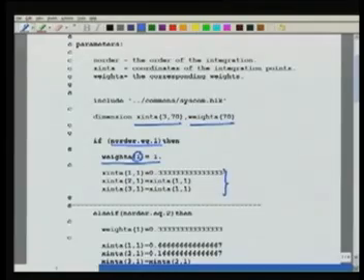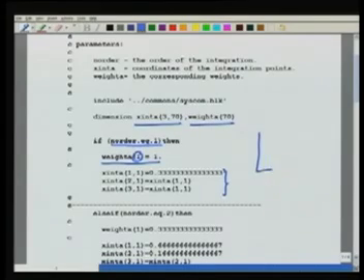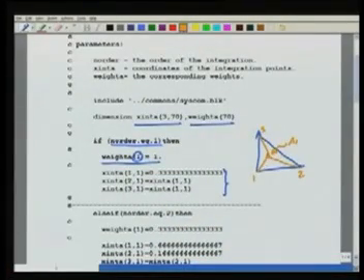given, has 3 coordinates, but we had only psi, eta. These 3 are actually given in terms of what is called the area coordinates or the barycentric coordinates, okay, which is very simple. Let's take any point, and this is my node 1, node 2, node 3. Connect these points. This becomes my area A1. So given any point in the middle or anywhere inside the master triangle, I connect that point to the 3 vertices. The area opposite to a given vertex is given the name A1. This area becomes A2. This area becomes A3.